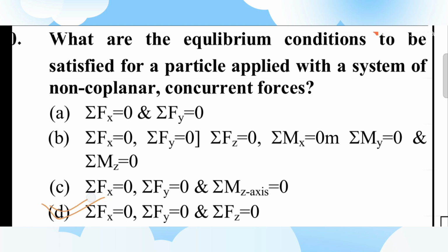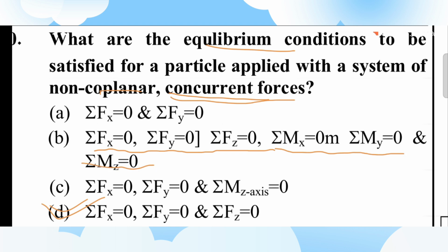Option D is right. This is concurrent force. For this concurrent, non-coplanar force, summation Fx 0, Fy 0 and summation Fz 0 is the equilibrium condition. If there is a non-coplanar non-concurrent force, then B is the answer. Fx 0, Fy 0, Fz 0 and moments in the x, y and z directions are 0.